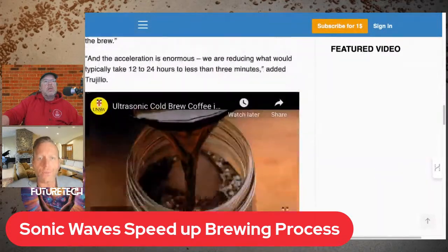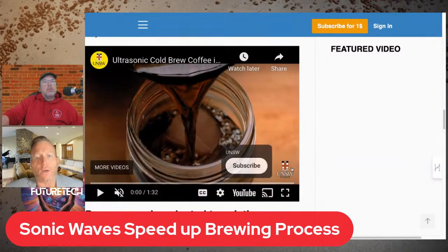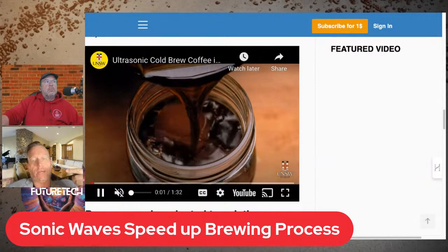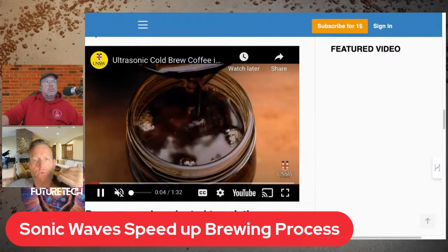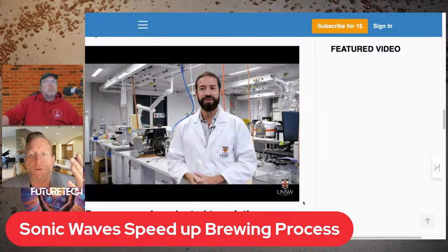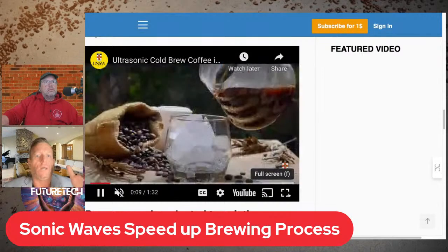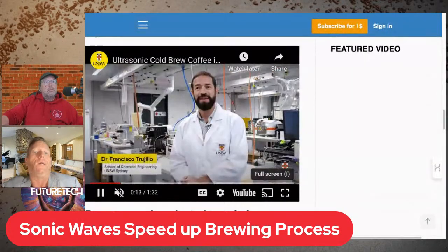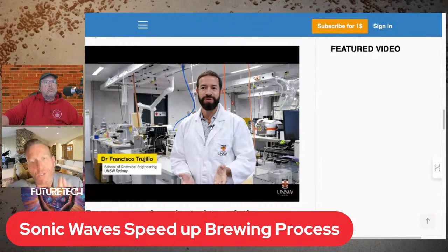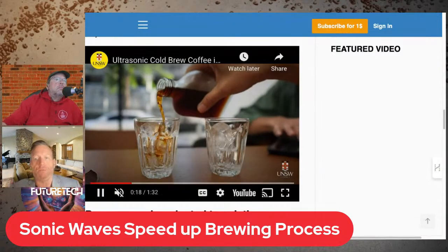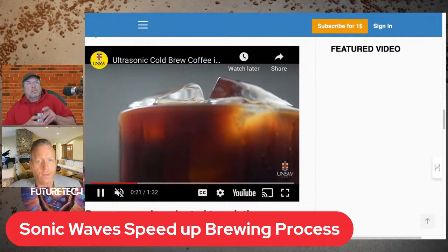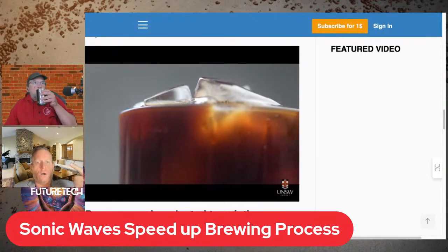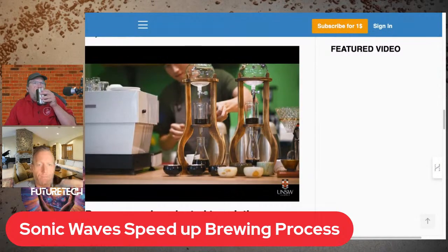The acoustic cavitation from the ultrasonic waves creates microjets that fracture the coffee grounds. The high frequency acoustic waves induce the formation and violent collapse of tiny bubbles. The collapsing bubbles generate shock waves and high-speed microjets. These microjets impinge on the coffee grounds, fracturing them to expose more of their surface area. The mixing action also helps disperse the grounds in the water, improving extraction.